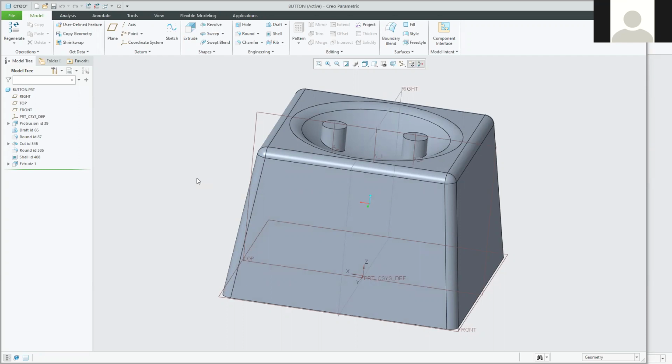I'm looking for info about, will there be any trapped air pockets within the mold? Will there be any places where the molten material ends up too hot and the material starts to degrade? Will there be any other problems when I injection mold this shape? Are there any other problems that I've not thought about that I could solve by either redesigning the part or picking a different material, let's say? So that's what you would use molding analysis to tell you. It's an analysis tool that runs a simulation of an injection molding process